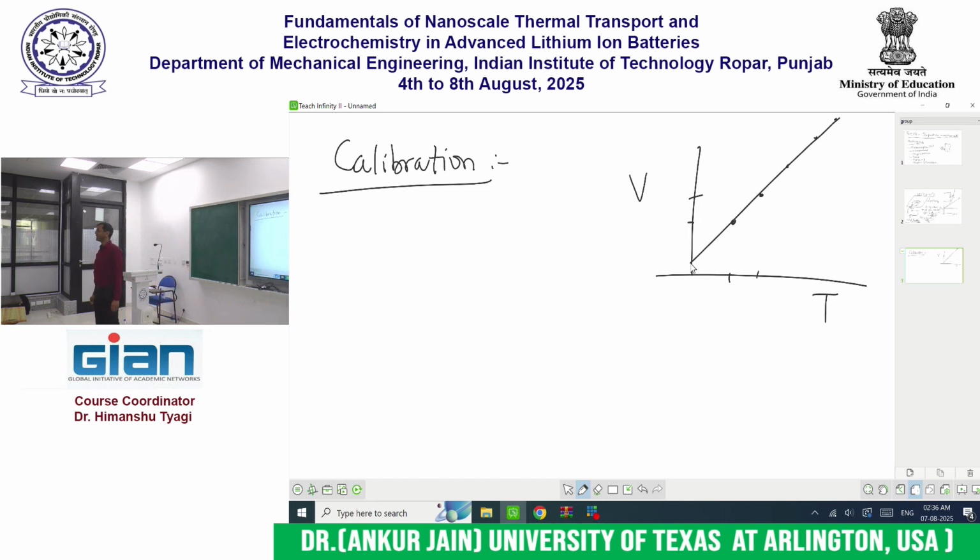Why is this calibration curve important to me? Because this calibration curve is my key to converting any future measurements of voltage into temperature. Right? Having taken these measurements, now I am confident that if I run my actual measurement and if the voltage turns out to be this, then the corresponding temperature is this much. You know what I'm saying?